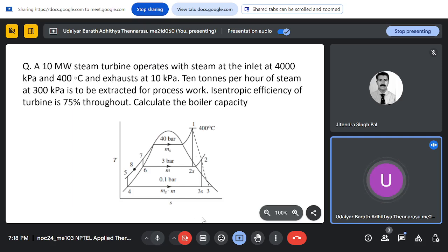So that is to cover the nozzle part. So the major part in the nozzle is the critical pressure ratio, which is 0.54 or (2 by gamma plus 1) to the power gamma by gamma minus 1. So that is the part. With that we can basically solve the nozzle problems.